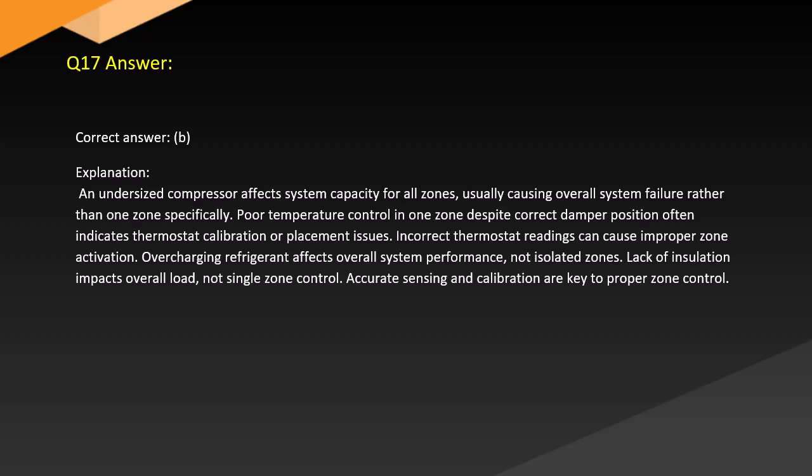Overcharging refrigerant affects overall system performance, not isolated zones. Lack of insulation impacts overall load, not single zone control. Accurate sensing and calibration are key to proper zone control.